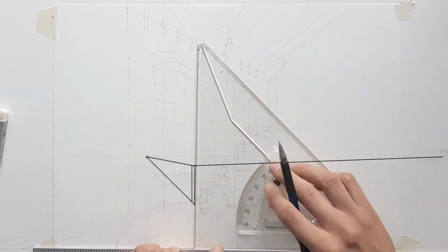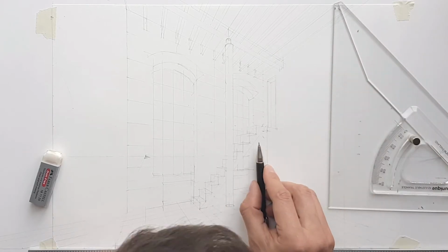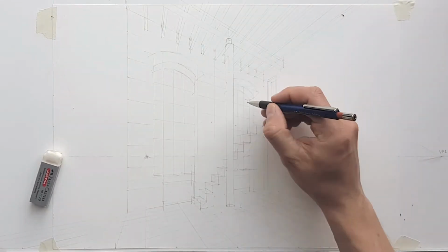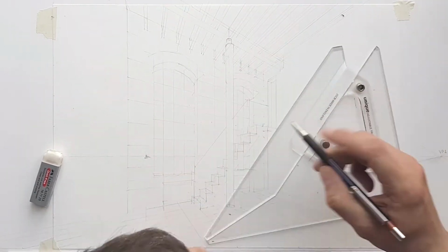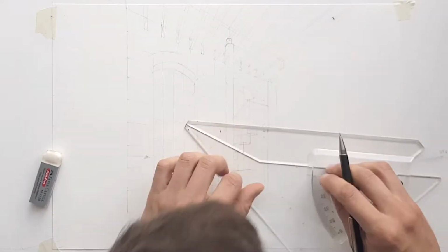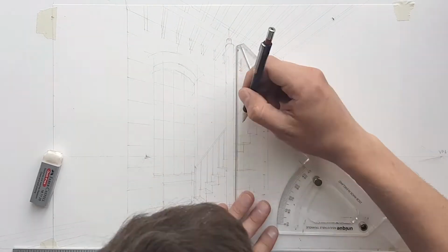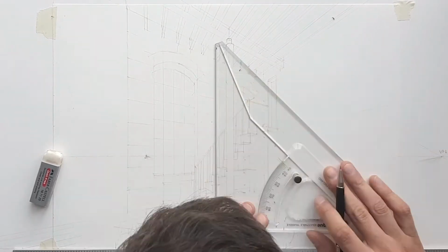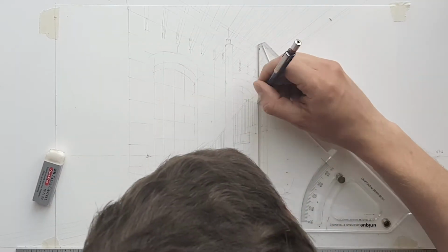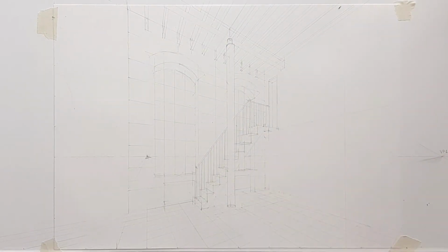And then following that, just drawing a railing, just projected at 1 meter height from the back wall to meet the nosing of the stair and also to meet the back of the landing. And then the 2 are connected and the thickness is drawn. So you can see the railings are at equal distances away from one another. And for that, they're drawn at the nosing of each step. Similarly, the top railing is divided.